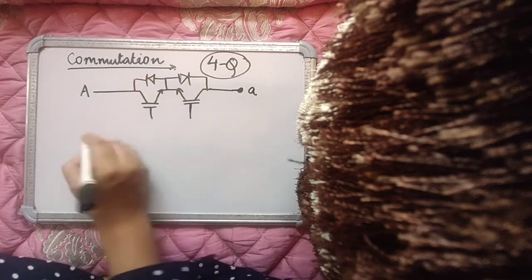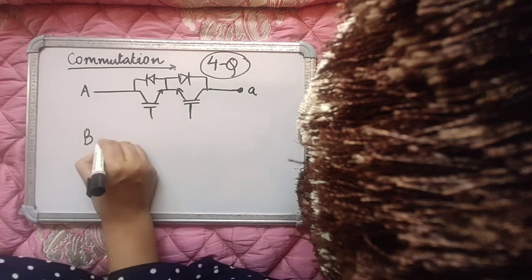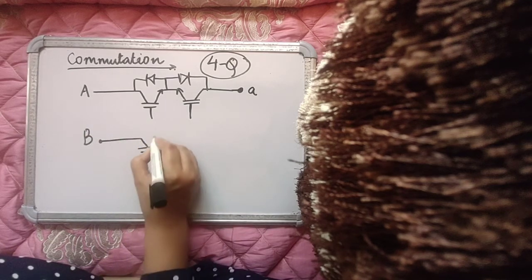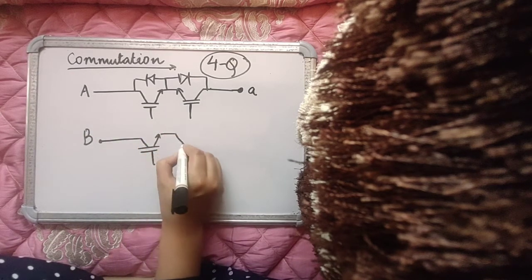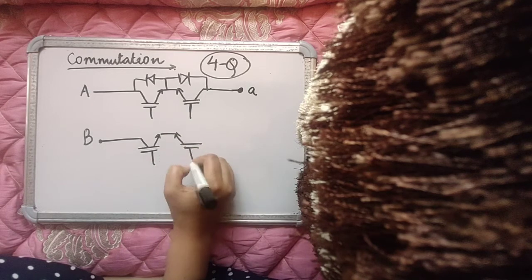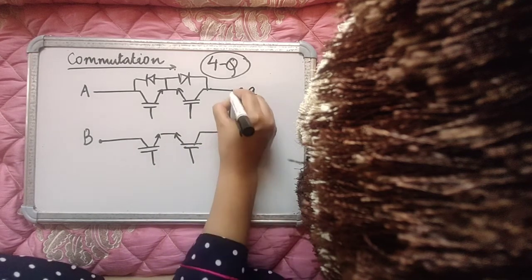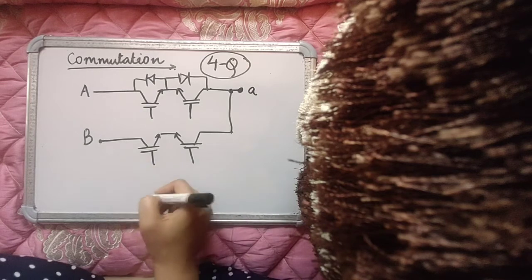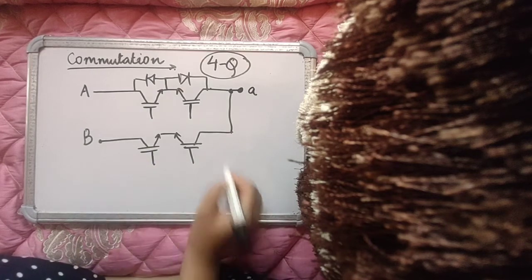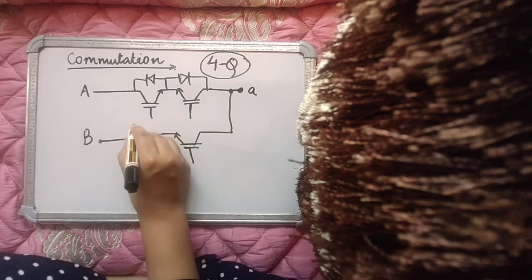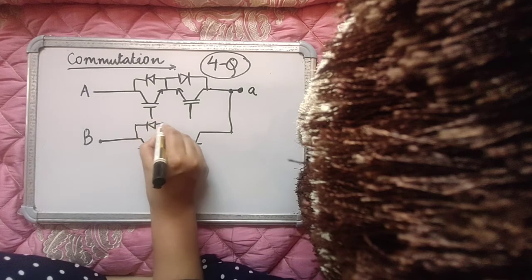So you have something like this, and then there is another switch that switches phase B at the output of the matrix converter, the same phase A. You will similarly have phase C in group A, and it will also be tied to the same output.